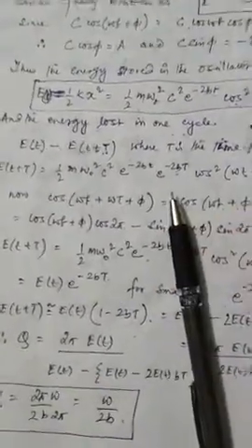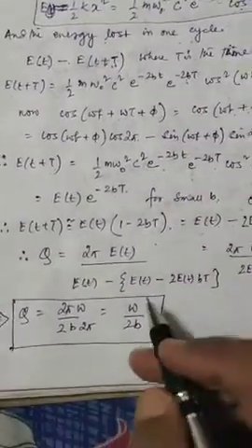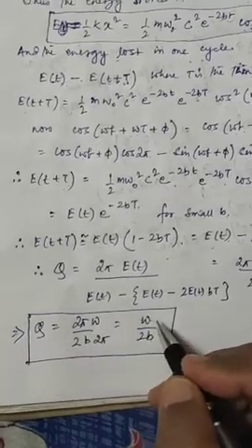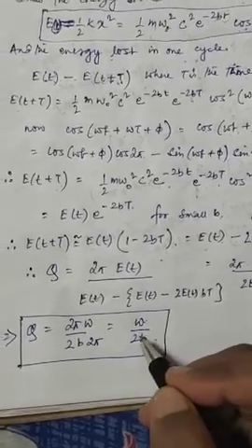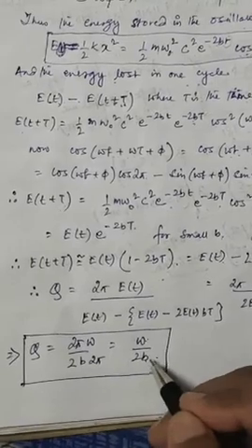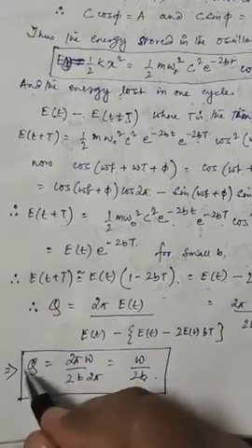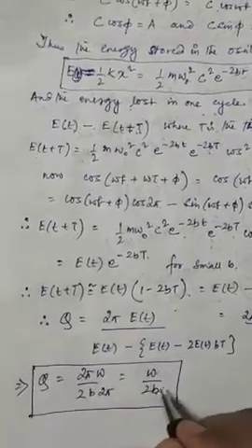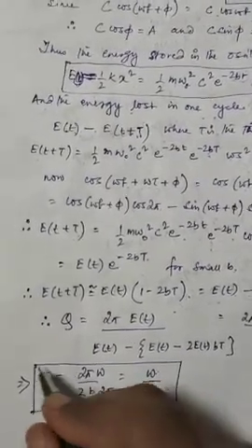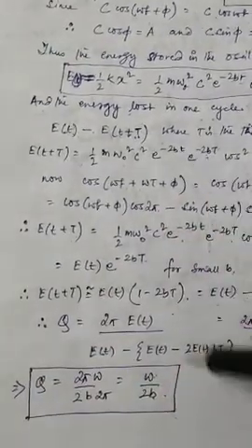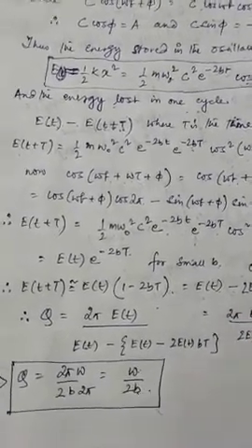So what is the quality factor? Finally, we have found the expression for the quality factor. This is going to be very, very important. The quality factor of an oscillator is omega by 2b. So you can see the damping is in the denominator again. So if the damping is large, that is energy is lost in the oscillation, then the quality of oscillation is poor. And if the damping is low, that is energy is not lost that much, then the quality of oscillation, that is the number of times it will oscillate before the energy reduces considerably, is going to be very high if b is small, and vice versa.